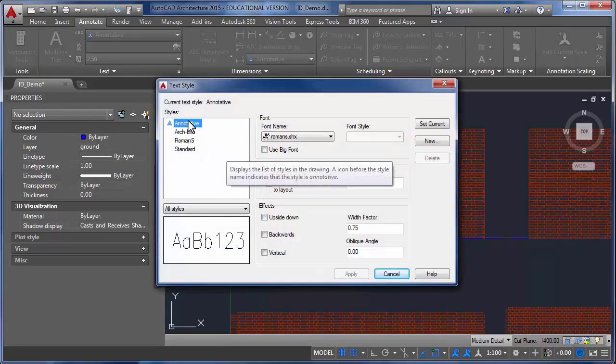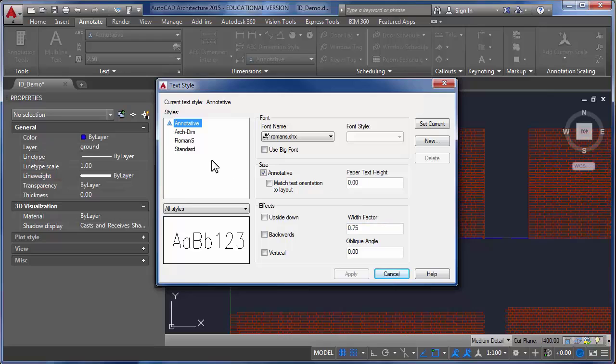This will bring up that list of all of those options here, and then all of the options we can change. One thing to pay attention to is this little end section view of an architectural scale. This is the feature we want to pay attention to. This is called annotative text. This is text that will change size, change its scale as we set scales in AutoCAD. So this is what we're going to do.